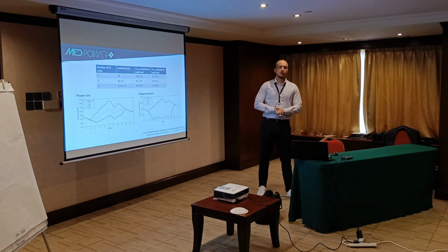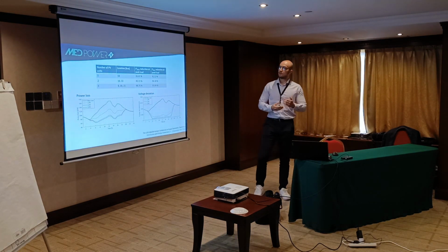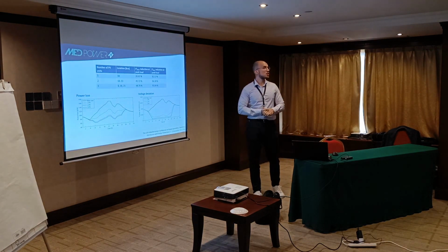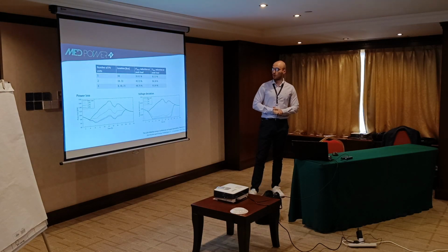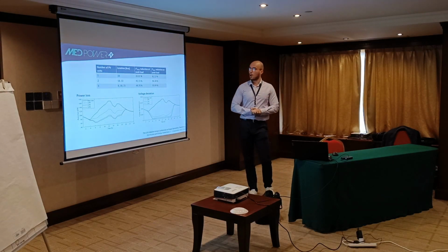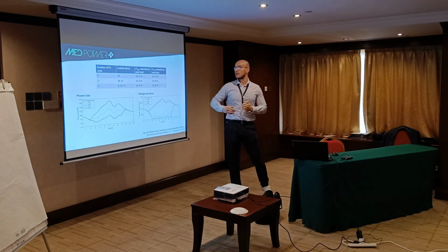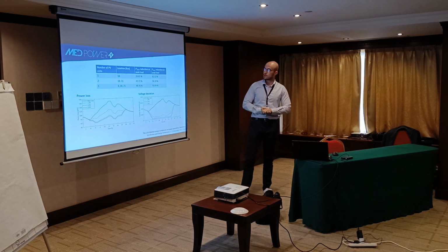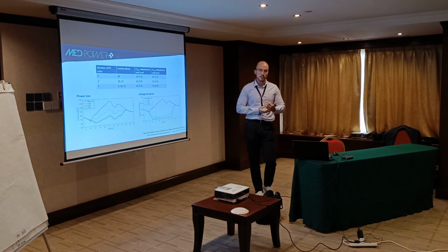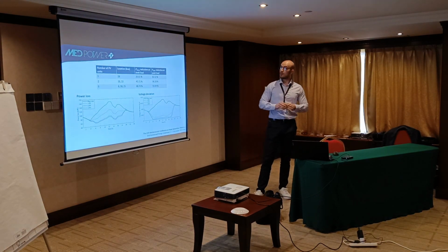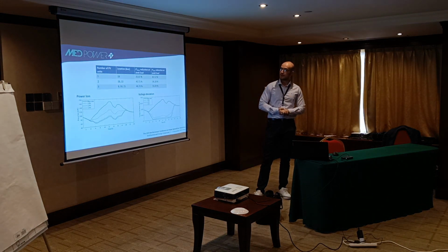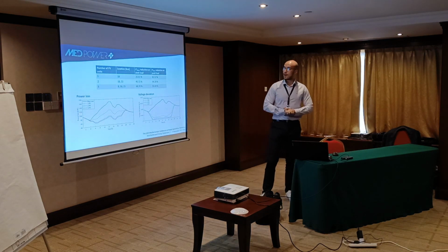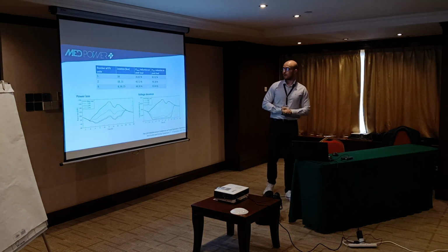We considered three scenarios, with 1 PV unit, 2 and 3 PV units allocated. You can see in the table the optimal locations for connecting these devices to our IEEE 33 bus system. Also, you can see the percentage of loss and voltage deviation reduction at peak load demand, which is very crucial. Those devices contribute to voltage improvement and loss reduction at peak load demand, and this effect increases with a higher number of optimally allocated units.